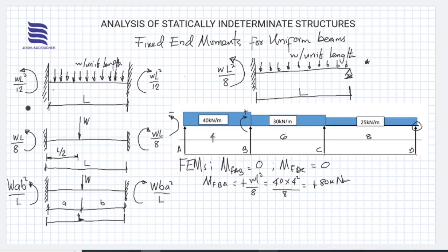So the fixed end moment for span BC, right? Of course this is going to be negative, being anti-clockwise, right? For span BC, of all these four fixed end moment diagrams, we have this to be representing that, seeing that the assumption for our moment distribution says that all our joints are rigid, so they're more like fixed, right?